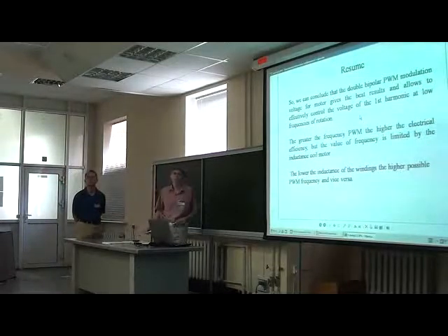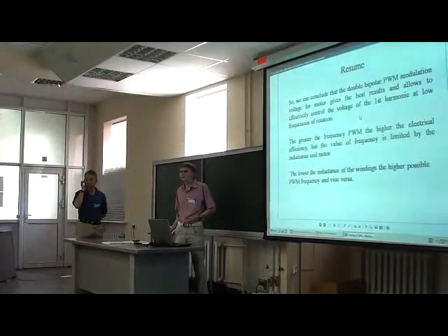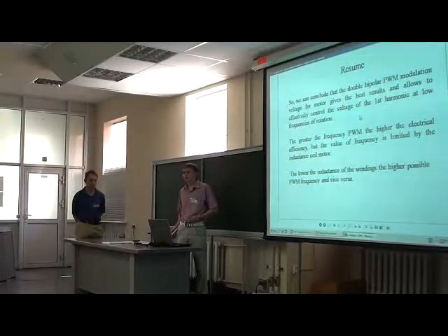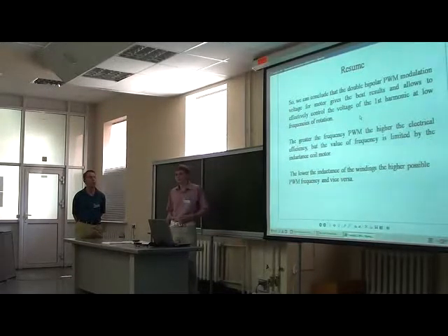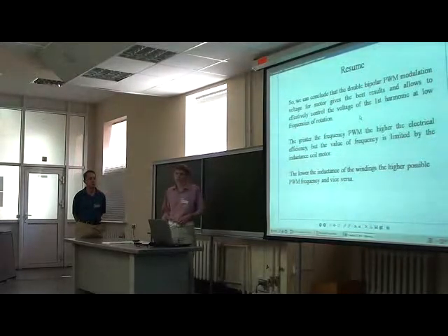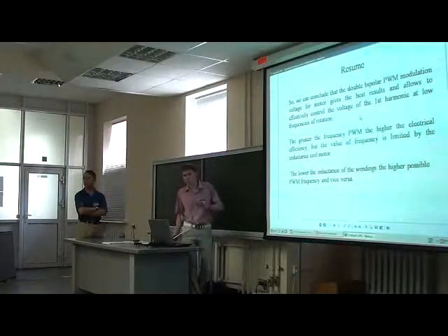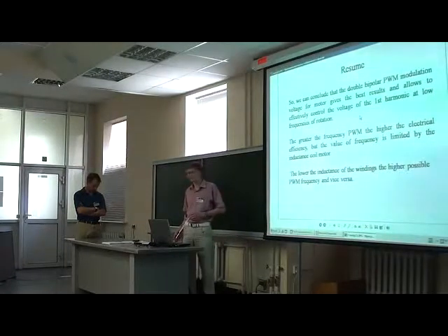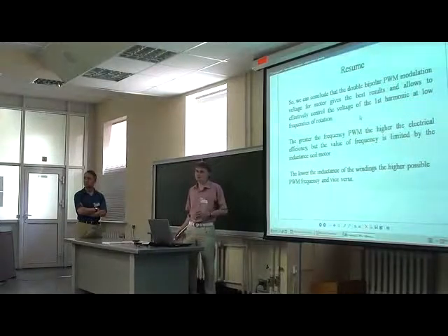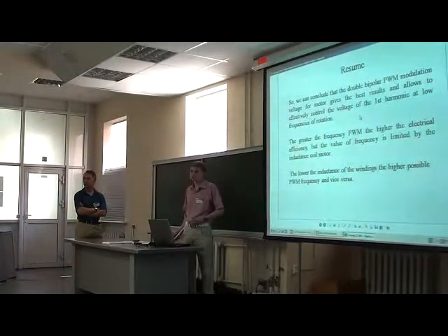I'm curious to know how small can you make them in your lab for other applications? Like 10 times smaller than this size? Yes, we can make that very small. With this method of bipolar PWM modulation, we can do it very small. But I can't answer exactly the value because it's different. It depends on the special motor, on the resistance, on the inductance of the windings of the motor.